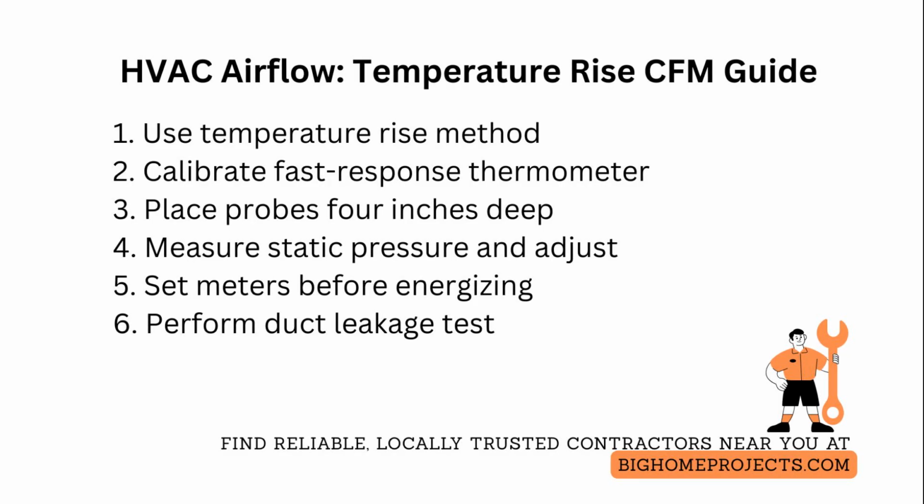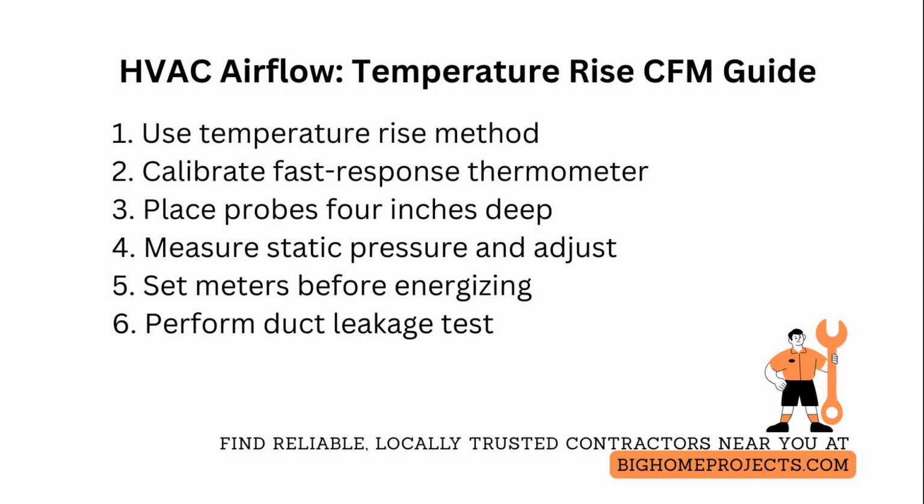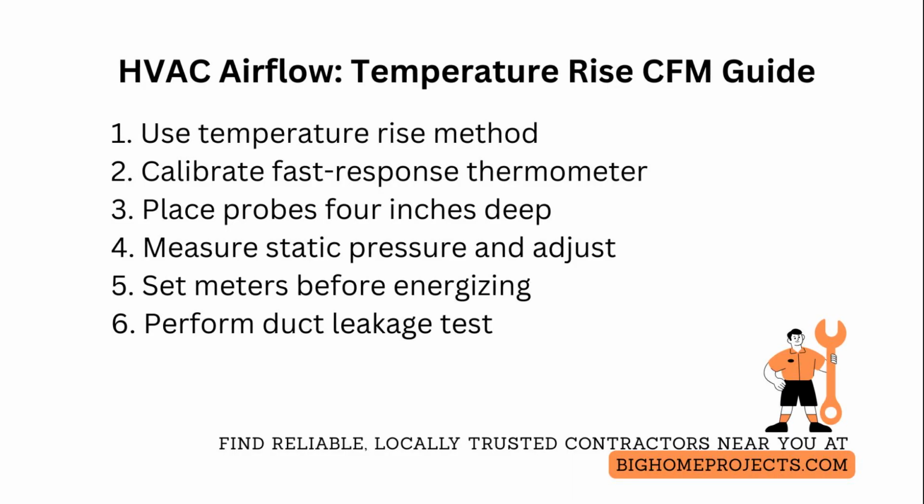To get heat gain, multiply equipment input in watts by 3.41 if using electric heat, or use sensible heat gain for gas systems from combustion charts. Always zero and calibrate your thermometer and ensure probes have fast response times.